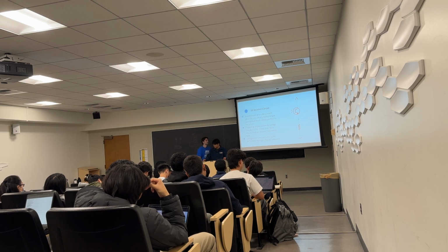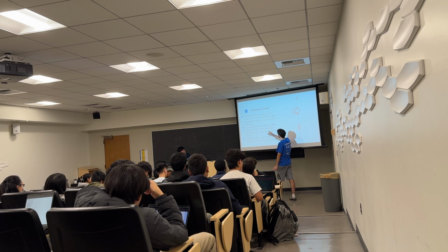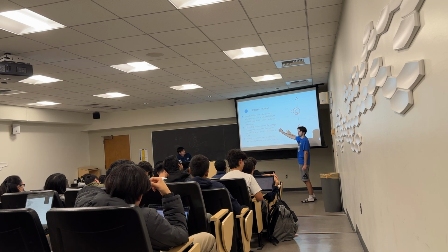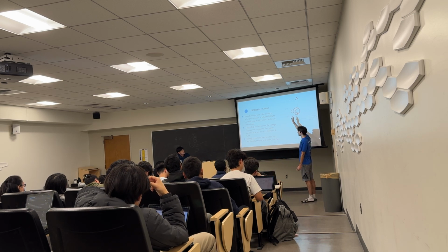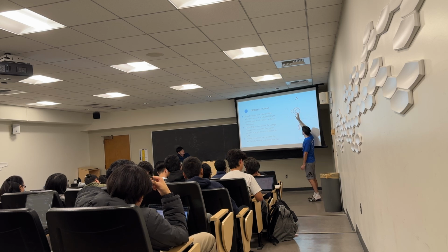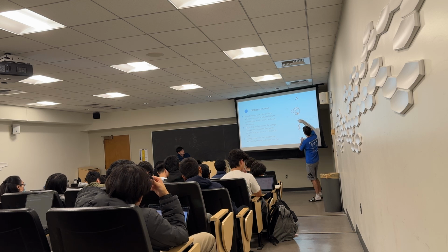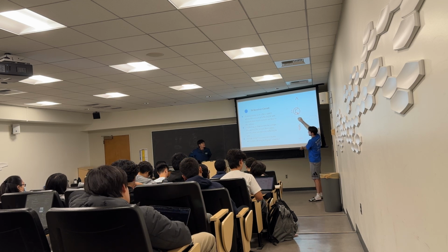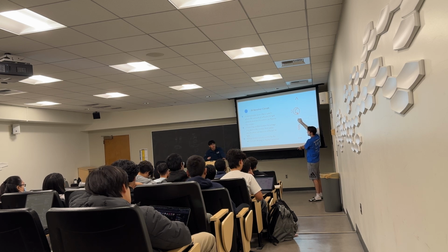So basically, the more reflected light the transistor receives, the more current is allowed to flow through here, and the greater the voltage drop across this resistor is going to be. So actually, you can imagine the greater the voltage is going to be right here, because of V equals IR. In case you don't know, V equals the voltage, I equals the current, and R is the resistance.